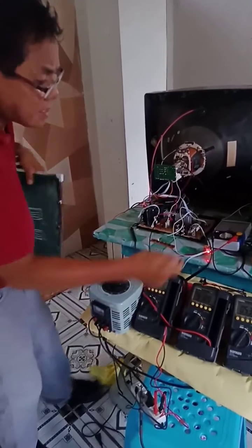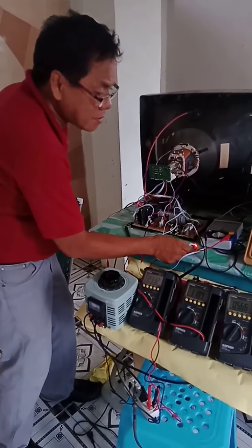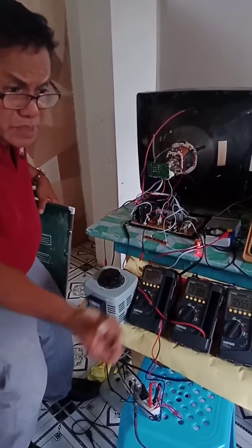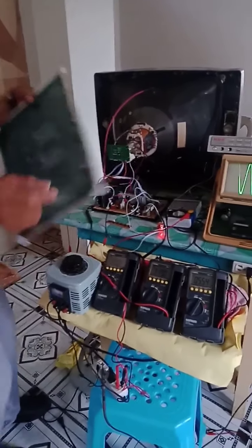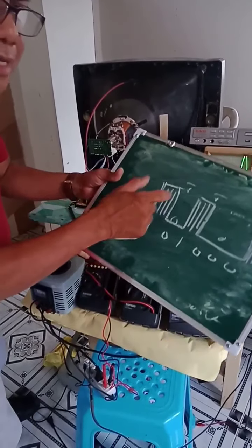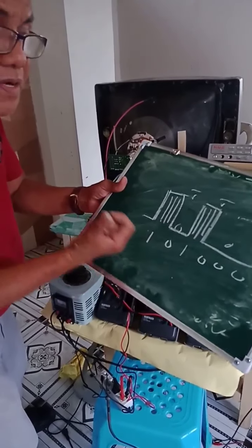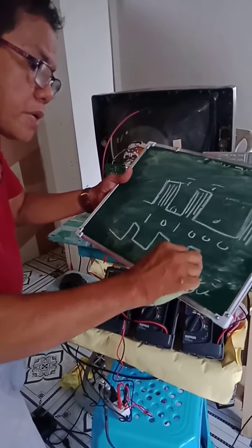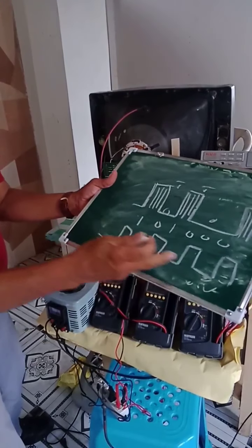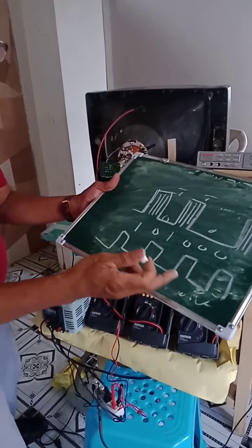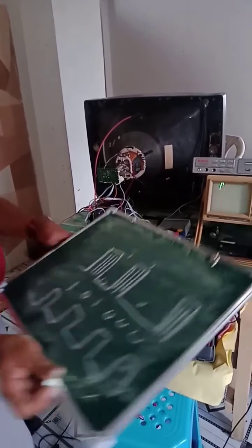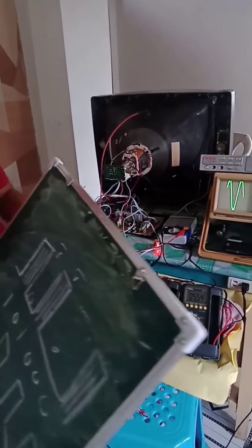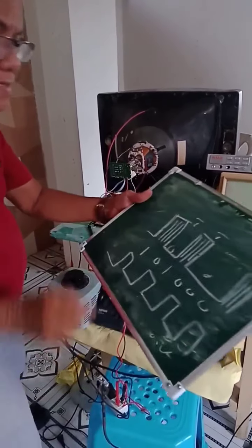But as it is received by the infrared sensor and submitted to the MPU circuit, this 38 kHz is demodulated and filtered out. What is fed to the microprocessor unit are the pulses only, containing the binary information. For example, volume up, volume down, channel up, channel down, different pulses.